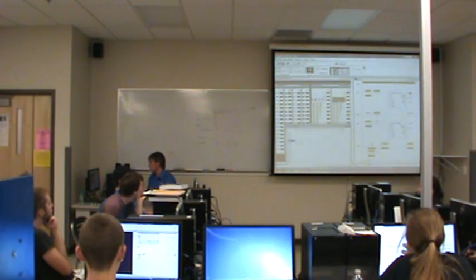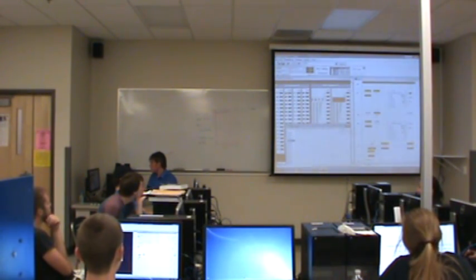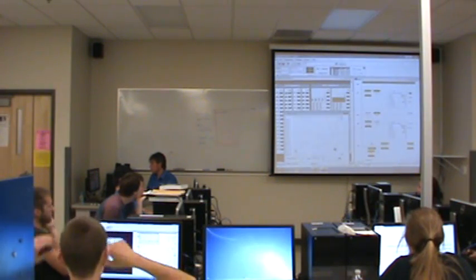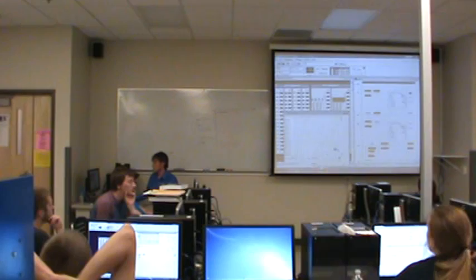Now it's looking for this bit pattern on the inputs. And when it's found, that causes the sequence output to go to the next step in the list and display what it has in its list, which is B3:12. That's why I turned off bit 0 and turned on bit 1, because that's exactly what this word says to do. Does that make any sense? It's starting to make more sense now?